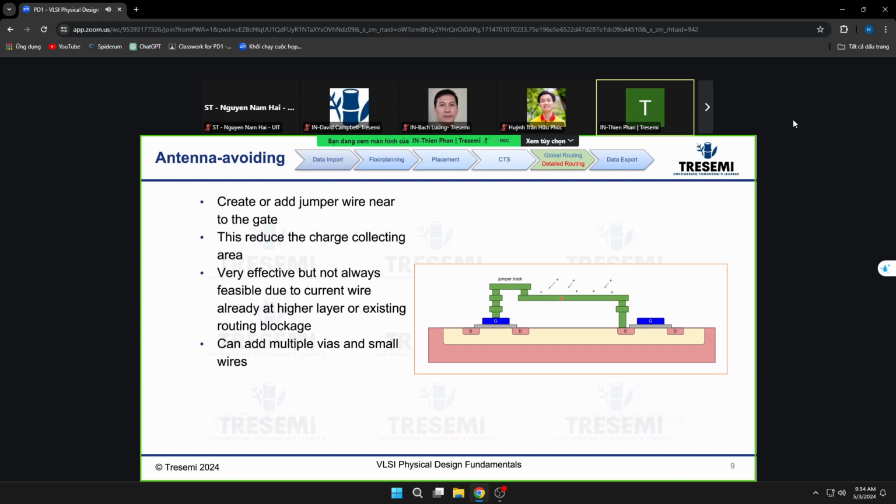So even though M2 is not the highest layer, realistically it is the highest layer for that area. Then you're very much stuck. You can't jump anymore, right? So sometimes you can't fix it with just the jumper, so we have to have a different method for doing that.